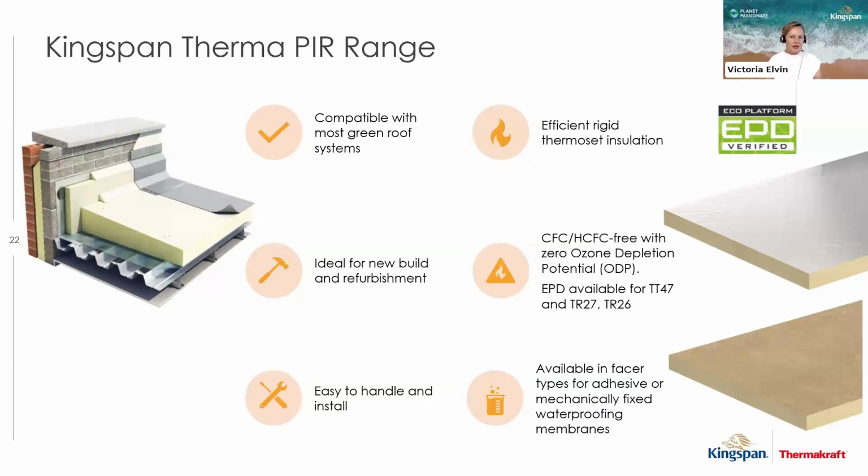The advantages of PIR include that it's an excellent insulator, it's a closed cell structure with a high resistance to moisture absorption, self-extinguishing in a fire, and does not melt. As I said, they simply char in a fire performance. Excellent durability, and they can be faced with different materials to provide different compatibilities with different membrane types.